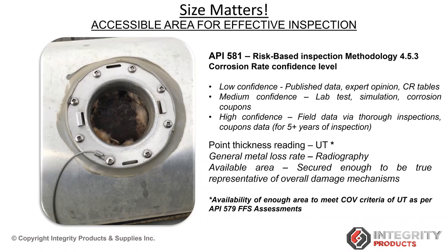So if you're just testing at one specific point, it's hard to say that data is representative of the rest of the line. Exactly. That's why there's certainly been a change in recent years towards much larger inspection ports where you can test over a larger area and get better, more accurate data. Absolutely. And that's why they recommend keeping it less than 10%, with as many data points as needed to keep the coefficient of variance.